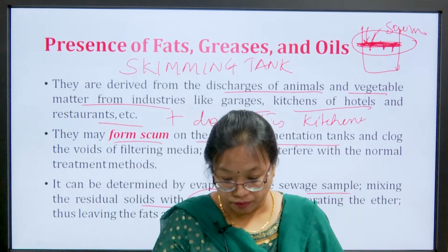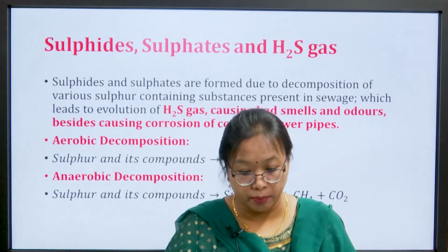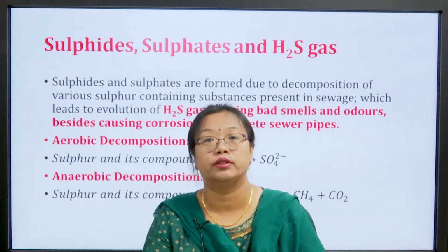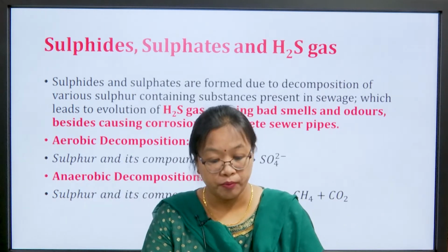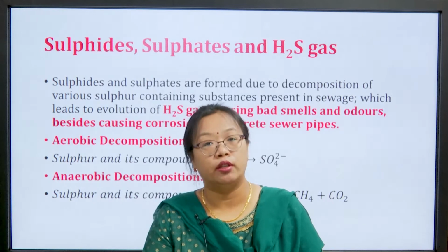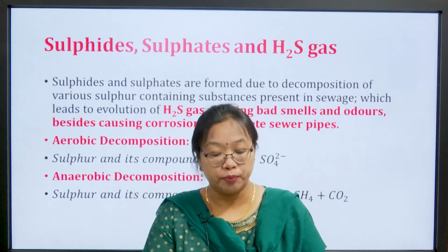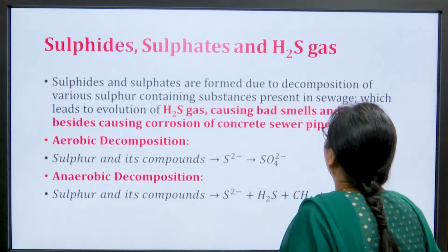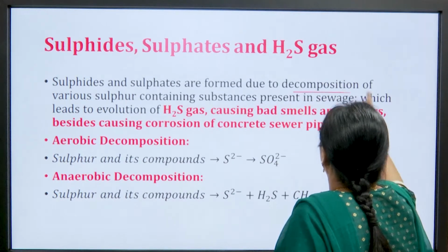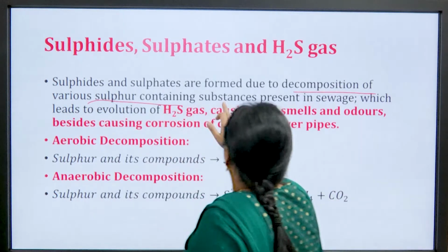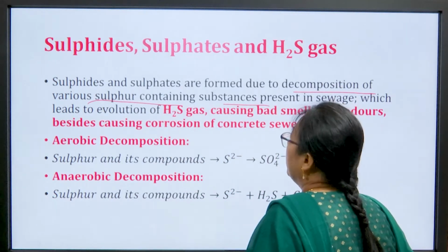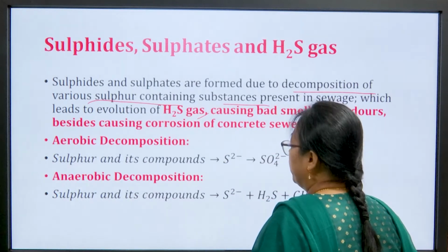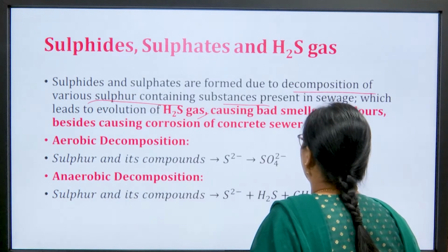So, now let us come to the next topic, that is sulfides, sulfates and H2S gases, that is hydrogen sulfide gases. We have already talked a little bit about this in water. Now, for wastewater, sulfides and sulfates are formed due to decomposition of various sulfur containing substances present in sewage, which leads to evaporation of H2S gases, causing bad smells and odors, besides causing corrosion of concrete sewer pipes.